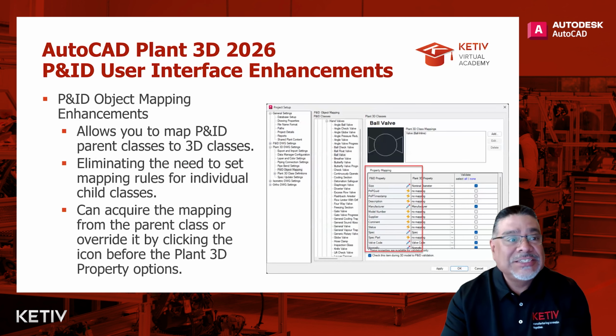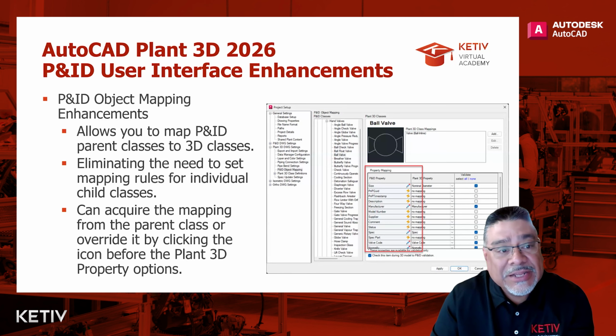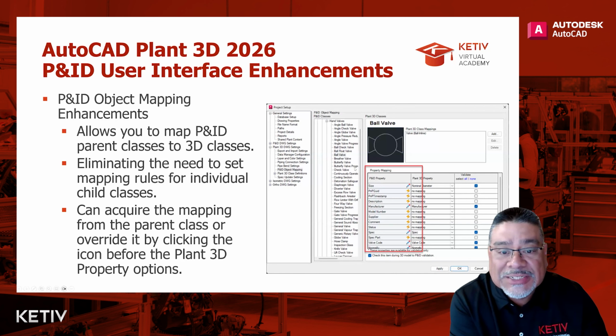So the other change that's happened here is within the project setup. If you notice over here, when you go into the project setup, you'd be going over here to your P&ID object mapping underneath your P&ID Plant 3D drawing settings. And here you would have your P&ID object mapping, your P&ID classes, and this is just showing the hand valves up here. But the one thing that has changed with this setup is that now it allows you to map P&ID parent classes to 3D classes with the change that's happened in 2026.